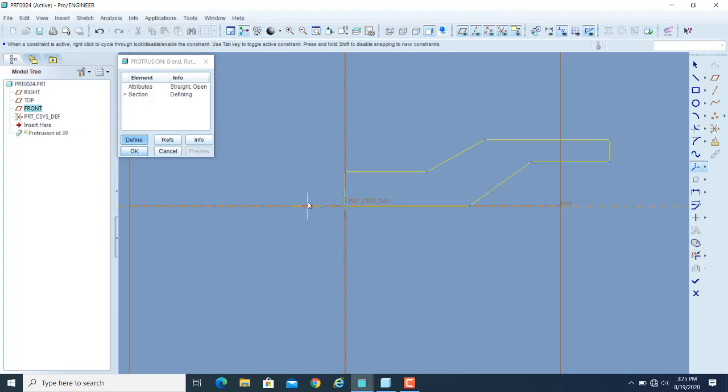For example, if I want to revolve this entity along this edge, I can pick this point as my axis of rotation, but in that case you will not have any internal circular hollow spacing in between the revolve object.